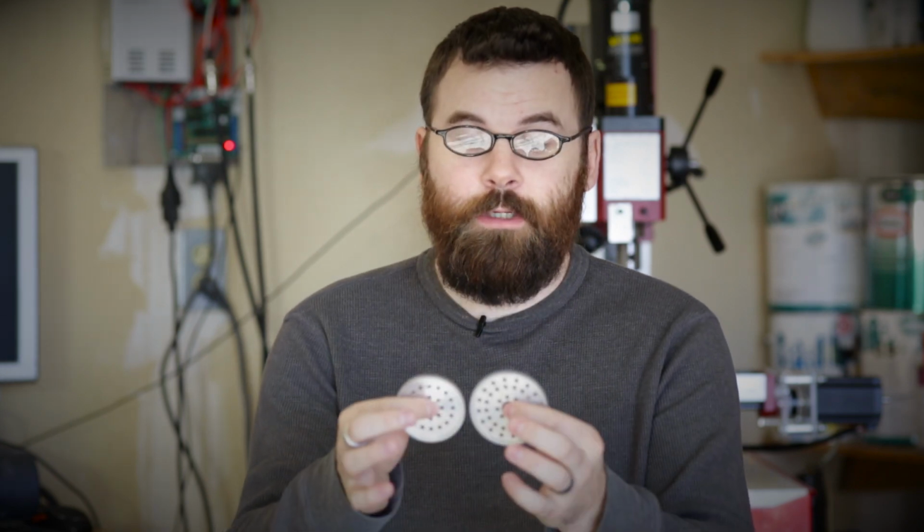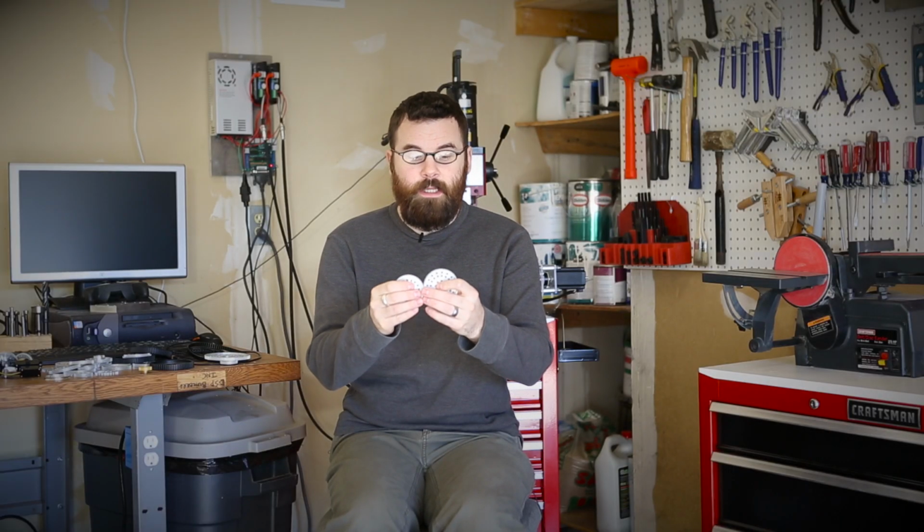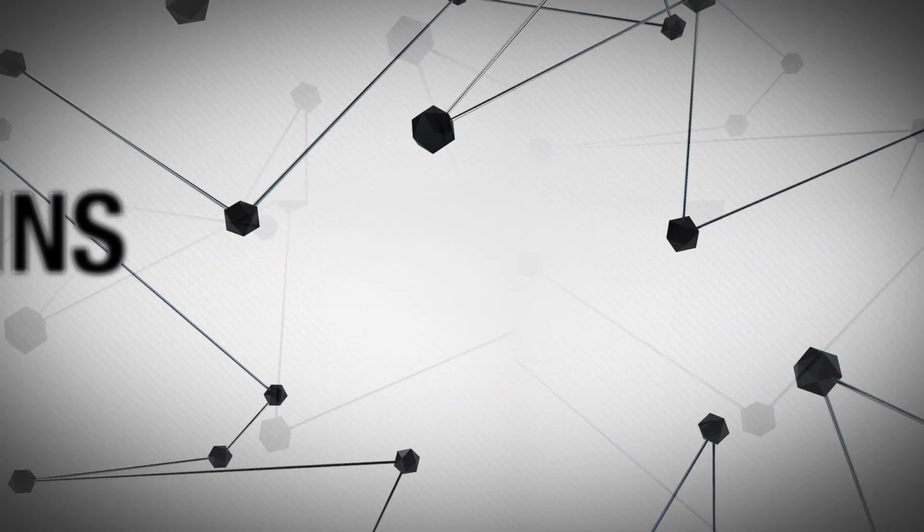Gears are very useful when you have a motor that is very close to the output drive shaft. Because there is a physical limitation of how close these need to be, that is one of the downsides to using gears, is they actually need to be precisely aligned next to each other to be useful. One of the benefits of using gears is because it is a physical mating between the two, you don't have a chain, you don't have a belt, the power transmission is very good and they're very robust and very reliable. You don't have to worry about a chain or a belt slipping off or breaking.